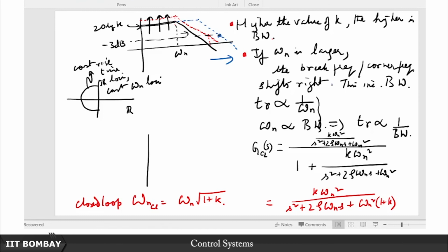These are things we understand intuitively, no? Because if you are putting a k block in front of an open loop transfer function, you are basically amplifying the input. So obviously the rate of rise of the output toward the application of an input is going to increase. That helps rise time, and it fits in with our understanding of bandwidth and its relationship with rise time.